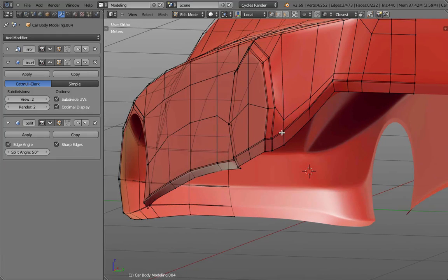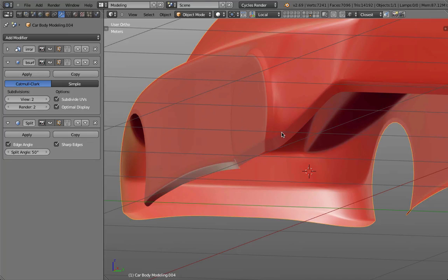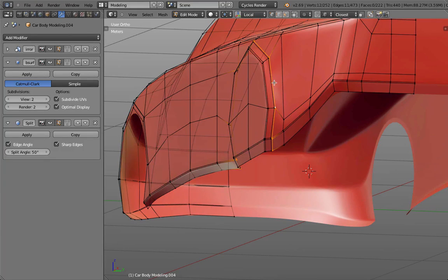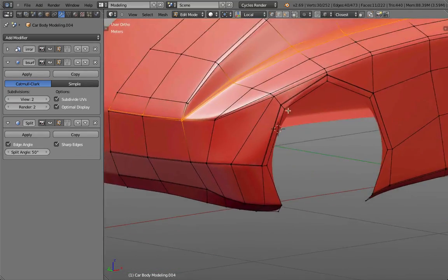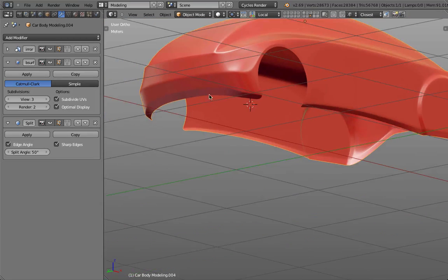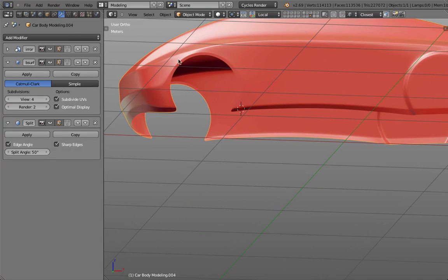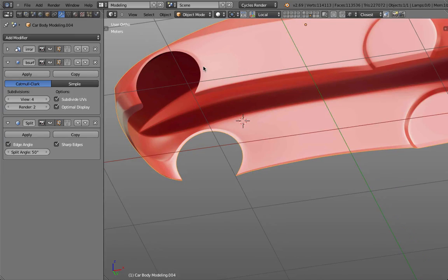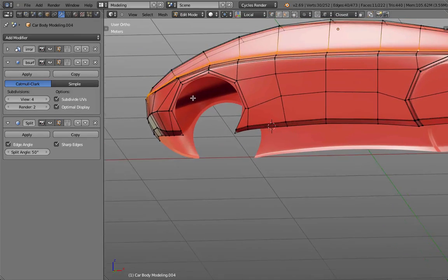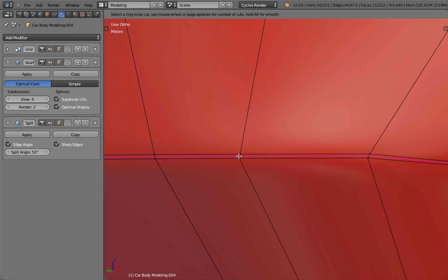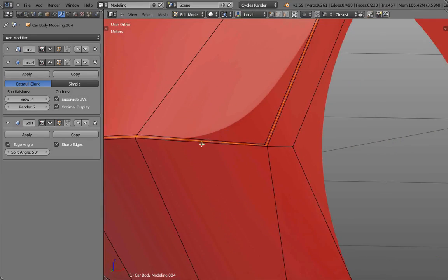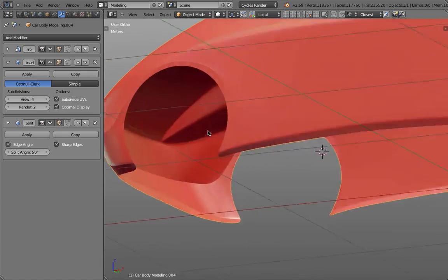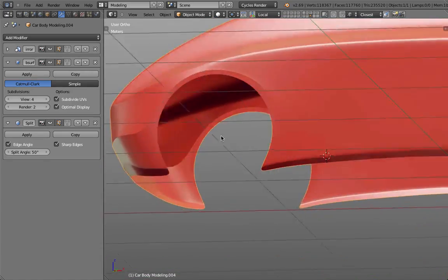And then based on how tight I want the surface to flow, I put those loop cuts closer together, for example here, or further apart, like here. If I make this one high, the front part is nice and creased. You can see how the surface goes over the wheel and then stops somewhere there. So I have a triangular part there. And if I want to get this even super crisp, I could, for example, add another loop cut. So I have 3 in between, and because they're very close, it just tightens it really nice.